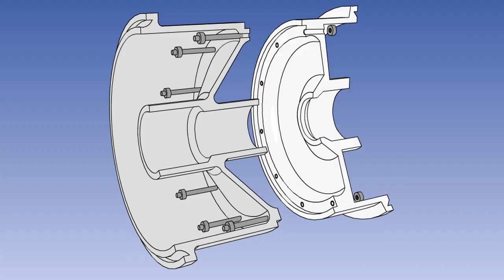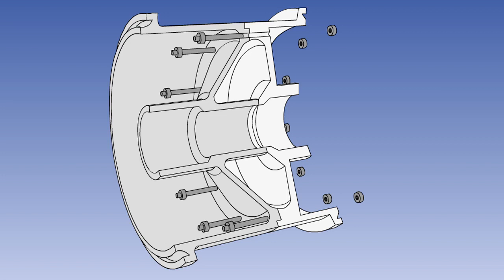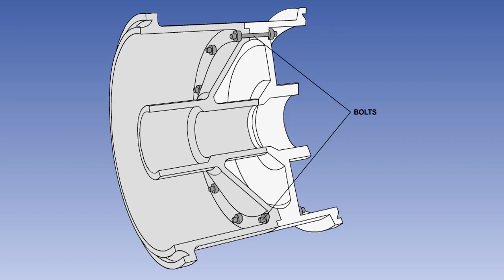The type of wheel most usually found on aircraft is the divided wheel. It consists of two half wheels matched up and joined together by bolts which pass through the two halves. The bolts are fitted with stiff nuts, or if one half of the wheel is tapped, that is to say that the bolt hole has an internal thread cut in it, then each bolt is locked with a locking plate.